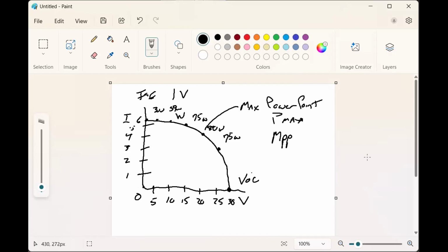In fact, if you were to test a solar panel with a meter without it attached to anything, you're measuring the VOC. It's not generating any power, but you can measure the voltage. You cannot measure amps unless power is flowing, because amps are current, and without motion, there's no current. So it's a theoretical measurement.